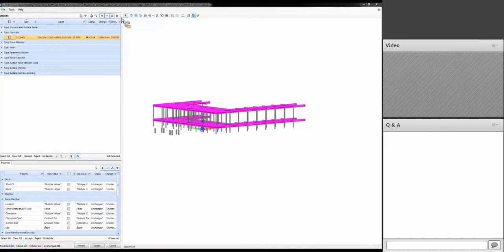Okay, next one. Is there a log or a list on the revision changes made on the model? So if you mean an itemized list of them, no, not in the revision manager itself. But what you can do is you can do a compare between the different states, and then it'll graphically show you, just like on the screen here, added, removed, changed. It'll show all those objects listed here that have changed compared from one revision state to the next. Okay, so it should be pretty obvious there when you use the revision management.